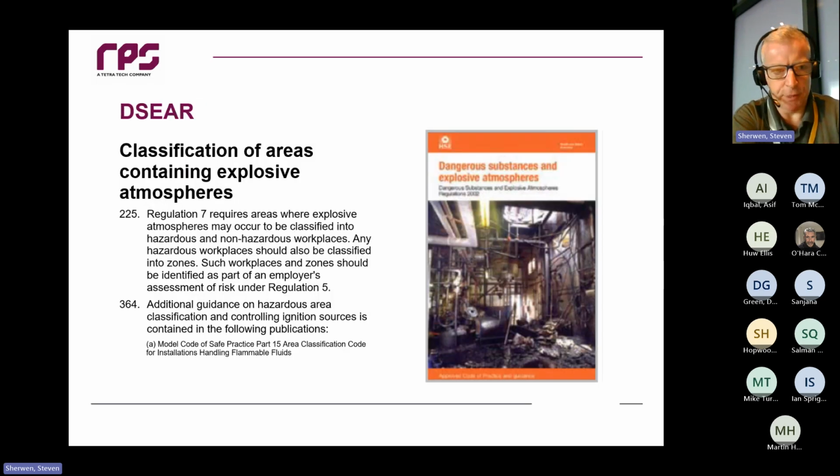So I probably don't need to spend too long talking about DSEAR to you guys, but as you probably know, DSEAR is the Dangerous Substances and Explosive Atmospheres Regulations, and it places an onus on employers to provide a safe place of work so that people are protected from the risk of fire and explosions and other energetic events. And Regulation 7 of DSEAR explicitly says that you should be using guidance, and you should demarcate areas where there are significant amounts of flammables into zones. Okay, and as I previously said, EI15 is one of those guidances to help you do that.